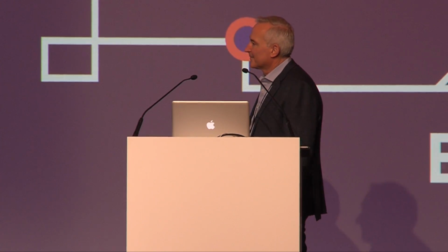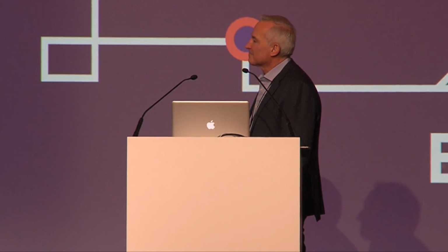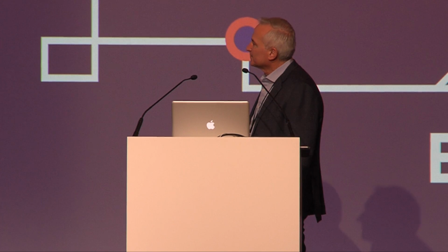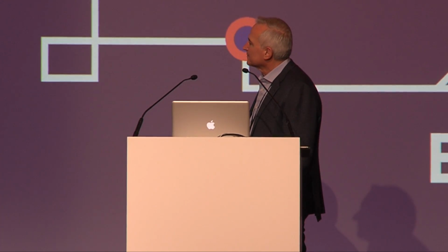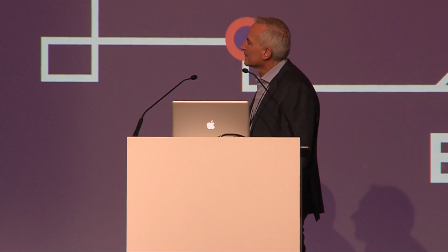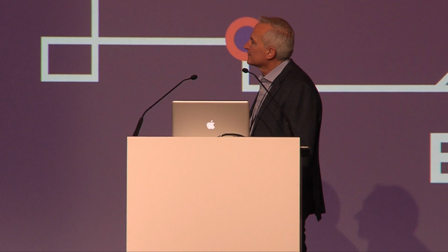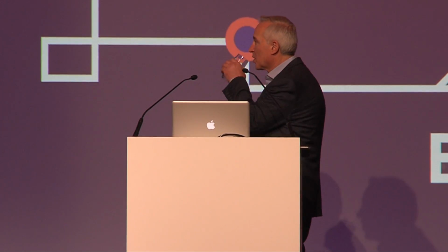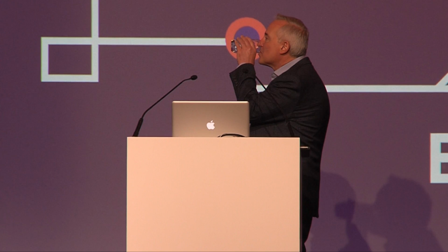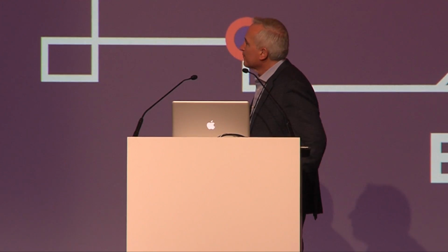And then maybe the configurable properties. I did not yet mention those, but you hover over this polyline, and it shows you the slope. Fine, but now at the bottom you see this tips dialog that came up, and it tells you that if I press my control key, then instead of selecting the entire polyline, it will select only one segment.